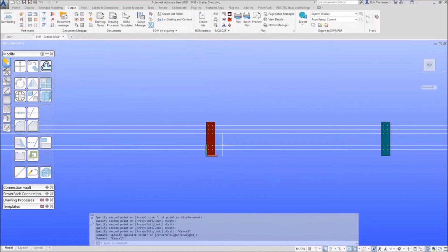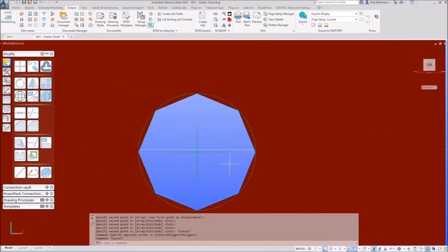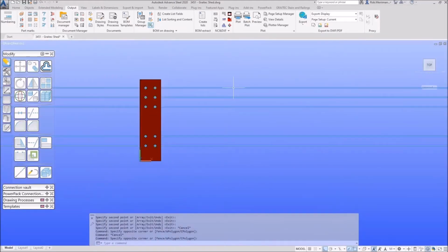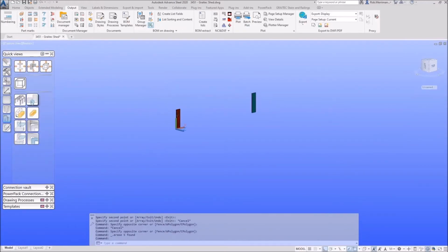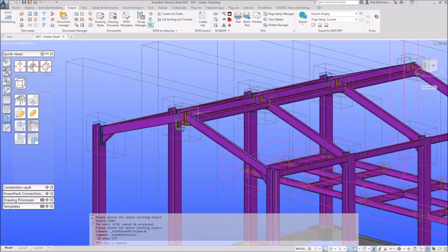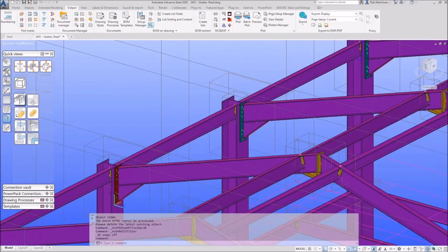We could have renumbered the model. This would get a different number, then we could number the changes. But what I've done in there is I've tweaked the holes, so those bottom holes are 0.5 mm different. So what I'm going to do to fix this is I'm not going to go into the joint dialog. I know this joint here is correct and I want this one to match it.